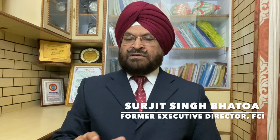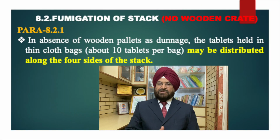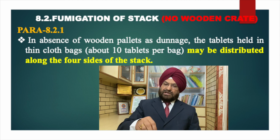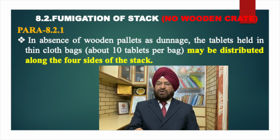The other case is when the stack is not placed on the wooden pallet. So what should the procedure be? In the absence of a wooden pallet as dunnage, the tablets are held in a thin cloth bag, putting 10 tablets in each. In Punjabi you can say it guthli, or in English it becomes a sachet.